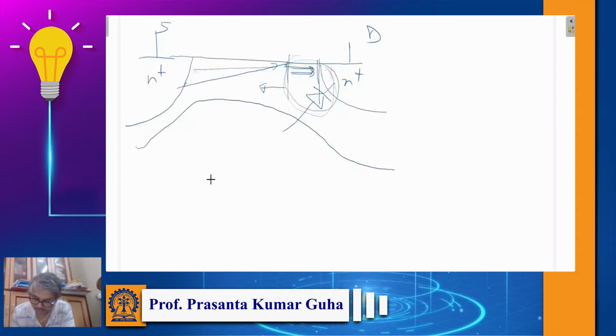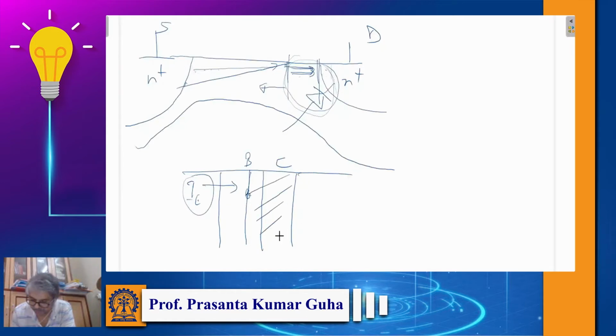You remember, in case of BJT, if this is the collector base junction, whatever current increase, current is coming from the emitter current, and once the carrier reaches here, the purpose of this depletion region is to drag those carriers to the collector. So at this point current is not increasing. Whatever current it has is because of the IE which is reaching this depletion region.